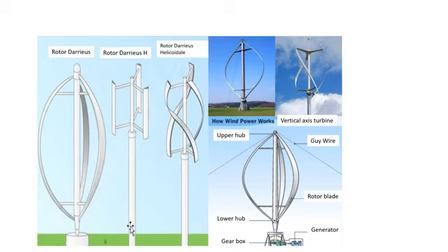On the other hand, there are some disadvantages too, which include the relatively low rotational speeds with the consequential high torque and hence higher cost of the drive train. The inherently lower power coefficient, the 360 degrees rotation of the airfoil within the wind flow during each cycle and hence highly dynamic loading on the blade. The pulsating torque generated by some rotor designs on the drivetrain and the difficulty of modeling the wind flow accurately and hence the challenges of analyzing and designing the rotor prior to fabricating a prototype.